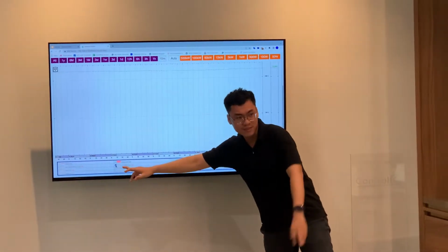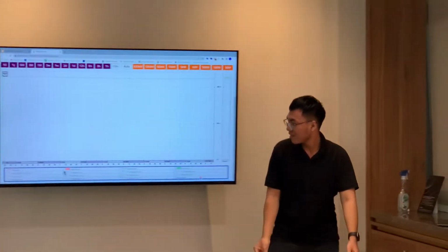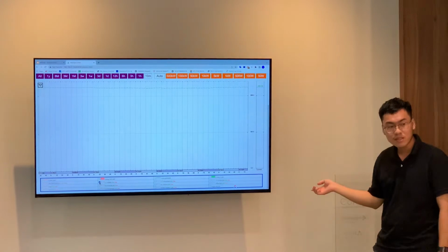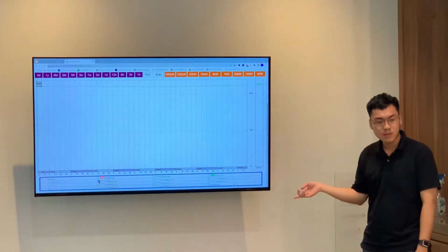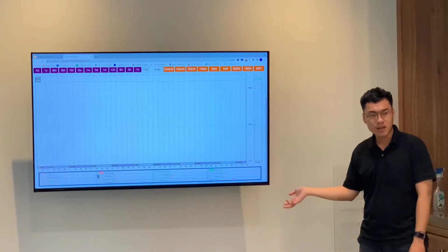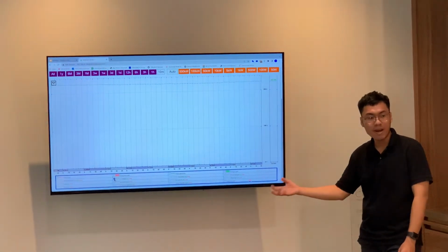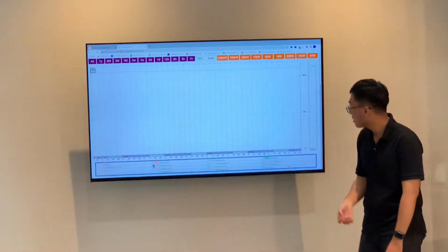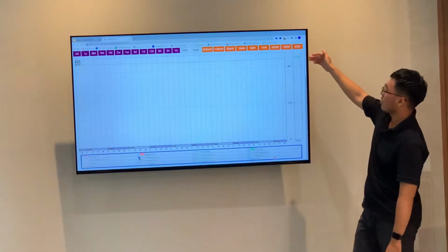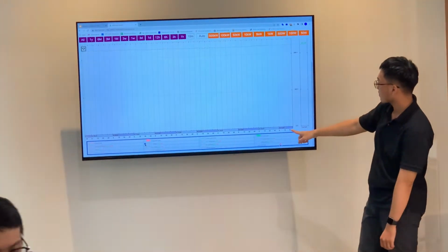L1 here, right? You can look at the smaller screen. That's the voltage input to the module. Like we just discussed, it supplies power to the eGauge and it also measures the power coming in. So it's around 200 milliamps here, you can see every second.